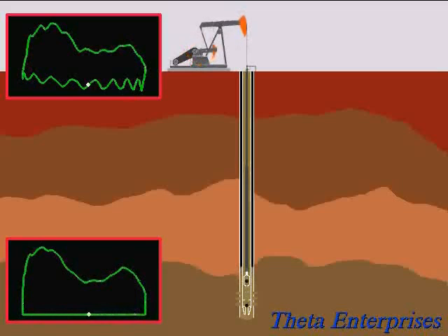Also, in shallow wells, we see more high frequency waves because the rod string has higher natural frequency. If I had that slinky that Andy was playing with yesterday, I could show you that. But it basically has to do with the rod string being stiffer, so it has higher frequency vibrations. That's very typical for shallow wells.